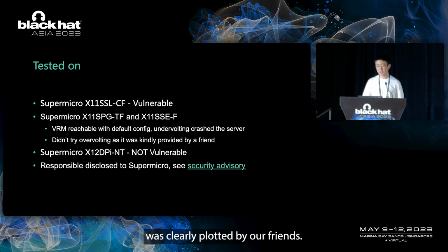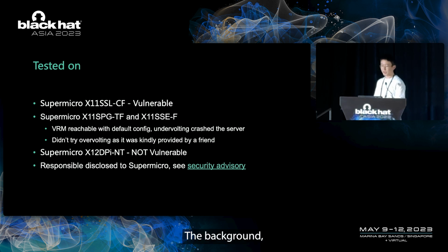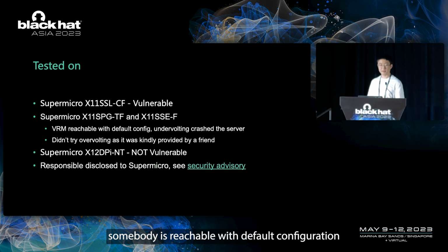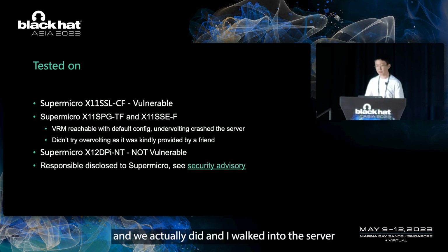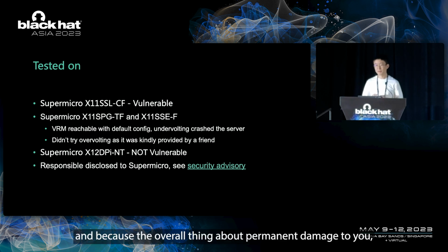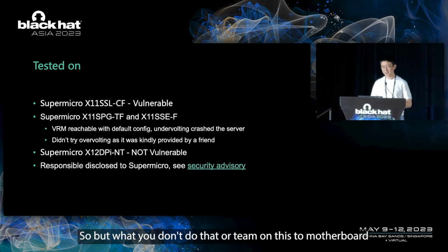These 2 motherboards were kindly provided by a friend with remote access, and we can confirm that the voltage regulator model is reachable with a default configuration, and we actually did undervolting to crash the server. Because overvolting will permanently damage the CPU, we didn't want to cost my friend a fortune, so we didn't do the overvolting on these 2 motherboards.